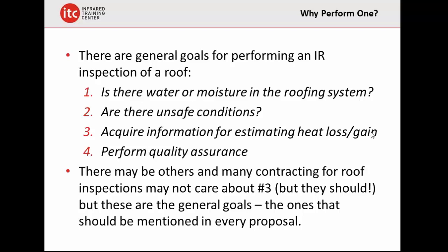So what you need to do is figure out the square feet. And once you know the square feet and the temperature differences, you can't necessarily do an instantaneous measurement of heat because you have a diurnal cycle, a 24-hour cycle of sun setting and sun rising. Personally, I wouldn't do it from the top side. I would do this from the inside and get a good estimate of the emissivity of the underdeck, measured in several different places. I would set the camera up on a program mode.